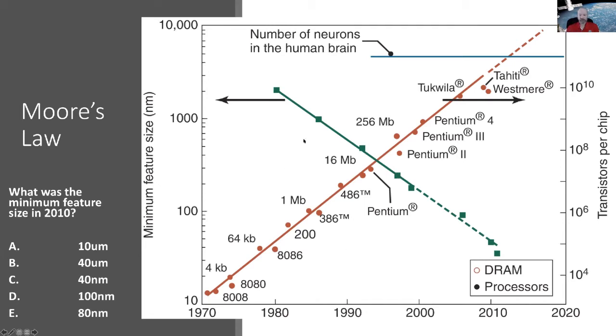And then we dropped, in the same amount of time, the minimum feature size quite a bit, to about 1/10 the size. So remember, if I make something half as big in X and half as big in Y, I can put 4 times as many in the same area. So shrinking something in half allows you to have four times the transistors. So that's what was driving this.